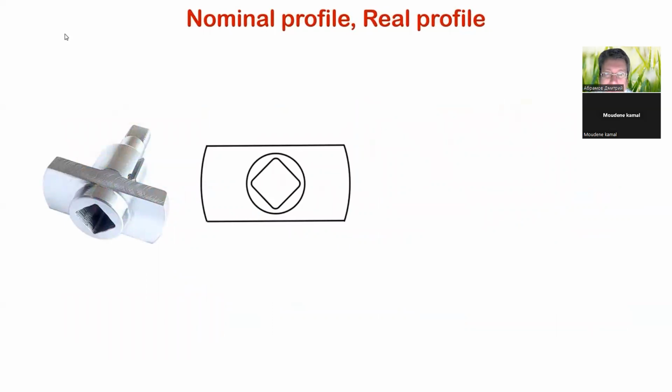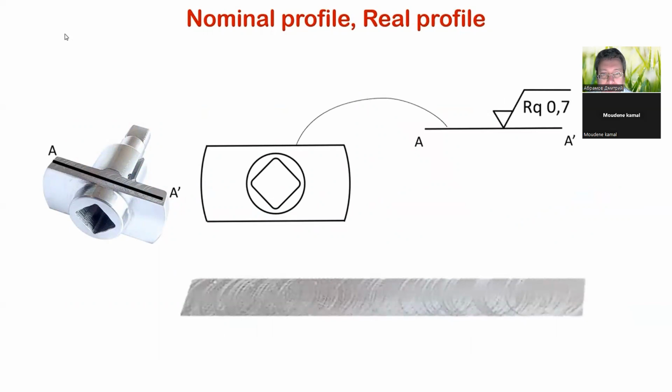On the drawing, he adds dimensional tolerances and surface texture tolerances. But before getting a profile on which the metrologist can calculate parameters, he must go through a conceptual stage which involves the theoretical profile on which tolerances are applied. The nominal profile is the theoretical profile, mentally constructed by the designer using a partition operation on the geometrical part. The partition is realized here by taking an intersection plane vertically through the volume of the workpiece and isolating the workpiece top, resulting in a rectilinear profile.